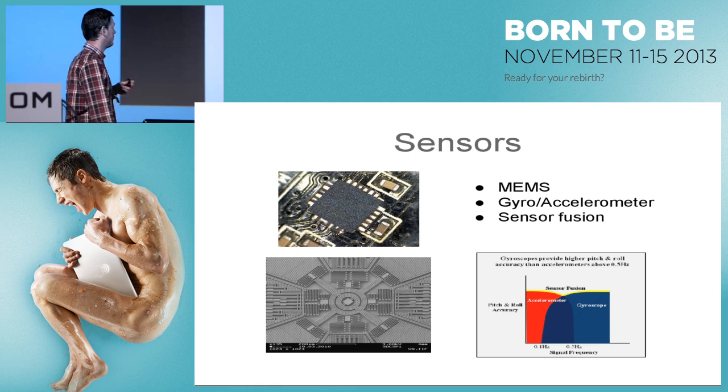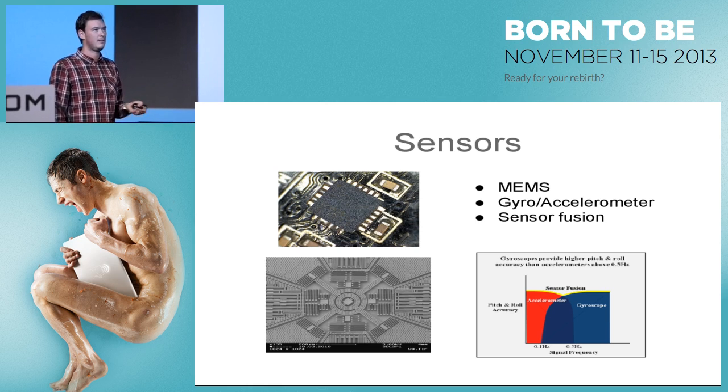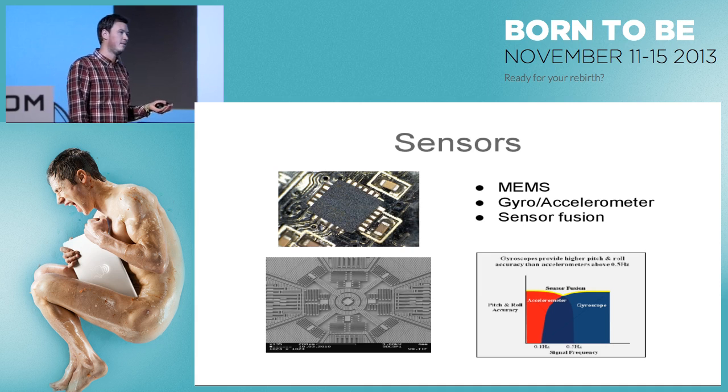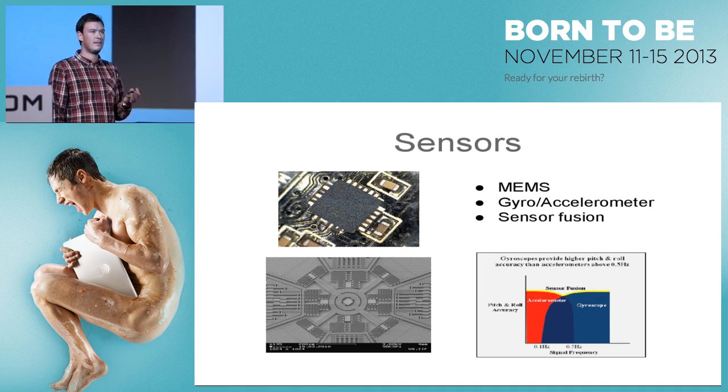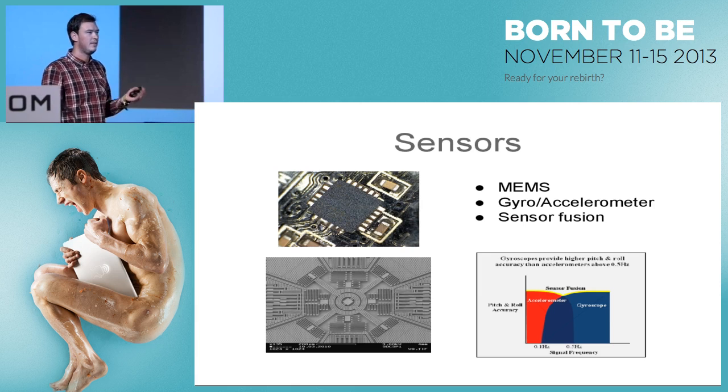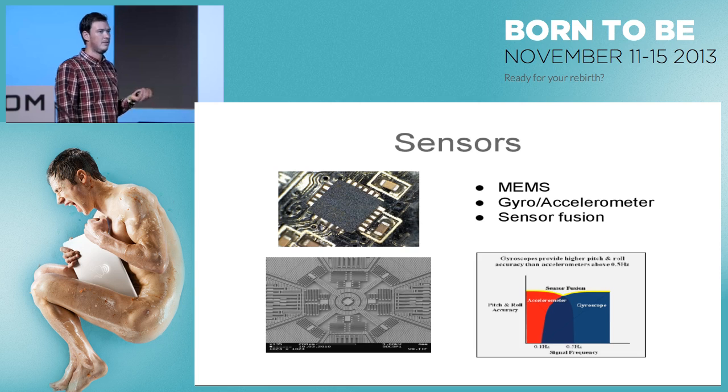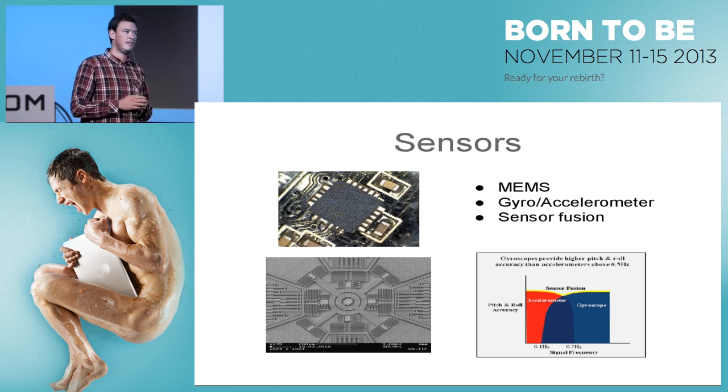With a gyroscope, you can measure the angular rate. That's actually enough to stabilize a quadcopter. But you really want to stabilize it around an angle. To get from an angular rate to an angle, you need to integrate it. And when you integrate it, you accumulate errors. So after a while, you start drifting, and your calculated angle will not be the real one.